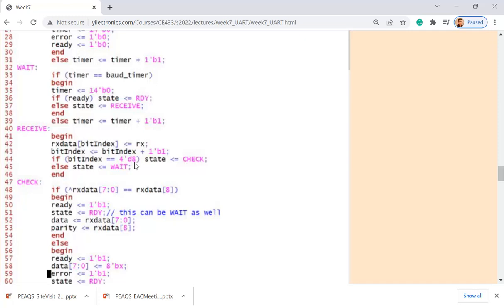So why do you have number 8? Keep in mind, in this example, we do have a parity bit. So you have 0 to 7, which are the 1 byte of data. So number 8 is the parity bit. You're asking, where's the start bit and stop bit? Why does it become 8 instead of 10 this time?